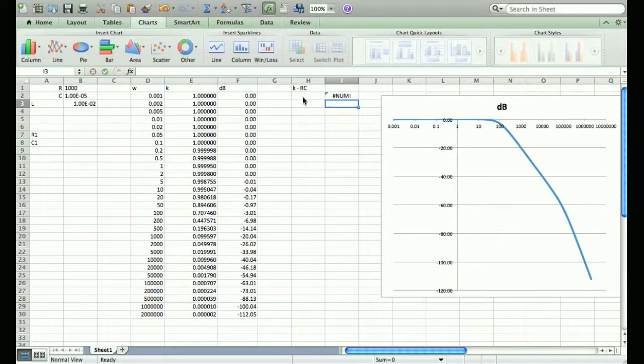Okay. Now that's because when you solve the characteristic equation for the roots, you end up getting S1 is negative 3.7K and S2 is equal to negative 2.68. So the cutoff frequencies are much closer than before.